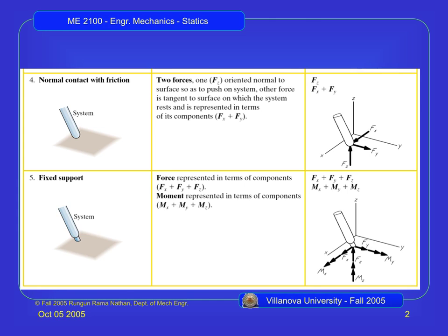So see these MX, MZ, and MY? Remember the FEMs in the last diagram, the reaction moments, preventing it from rotating the beam? That's the same thing. When you draw a double arrow at the end, it means that it's a reaction moment, not a reaction force. So these are forces preventing it from sliding left to right, sliding front to back, moving up and down. Here, this one cannot rotate at all. So it's not able to rotate about this axis, or about this axis.